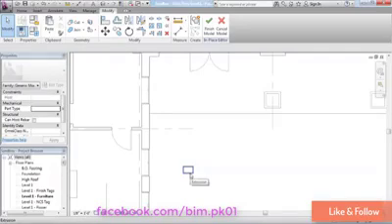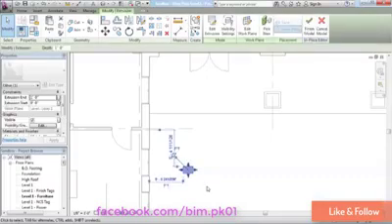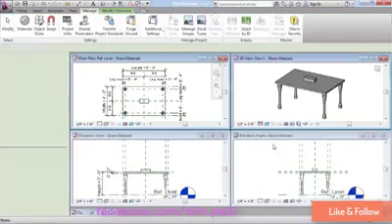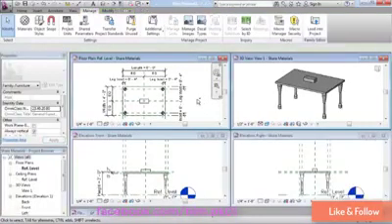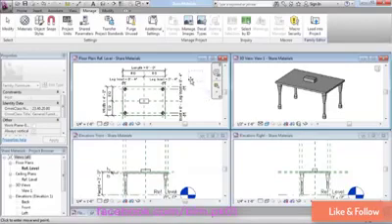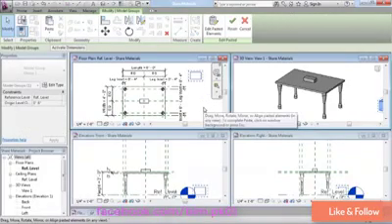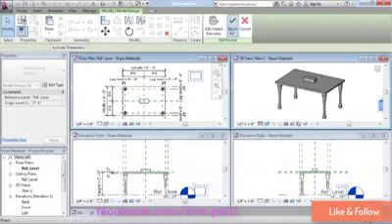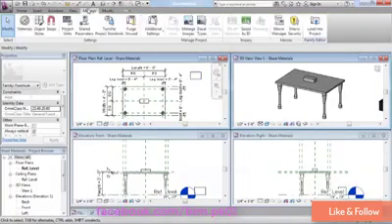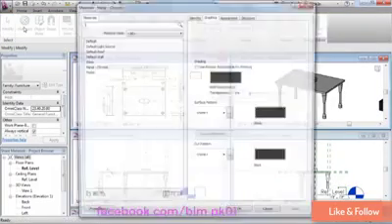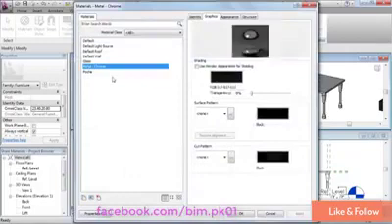Think of it like an envelope. It's the UPS guy. I'm going to select this thing, do Control-C, that puts it on my clipboard. Then I'm going to switch back over to my family here and just anywhere do Control-V, and I'm pasting that box into this other family. I'll finish the paste, and now if I go to Manage and I look at my material list, you're going to see that metal chrome has been brought over to this family.